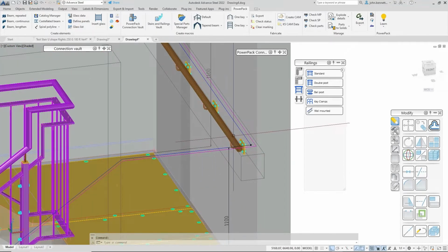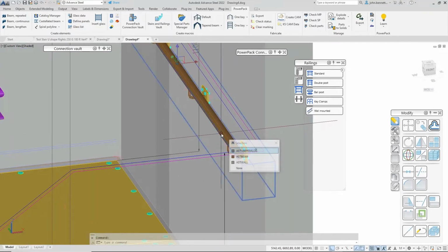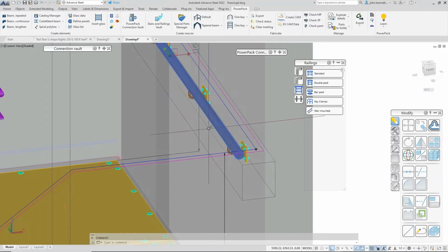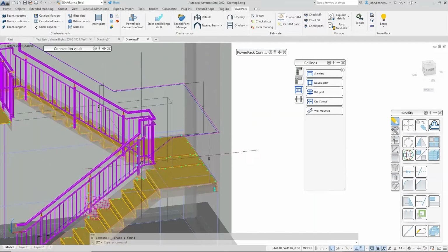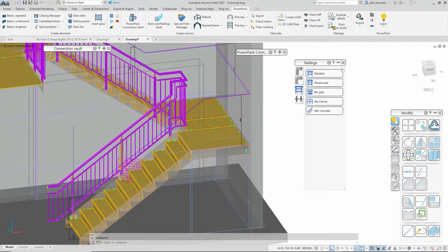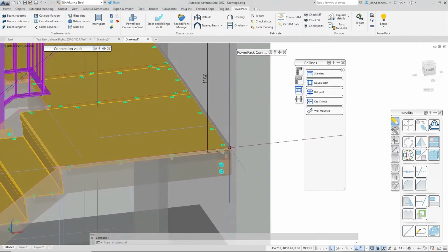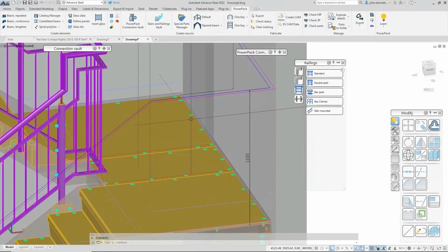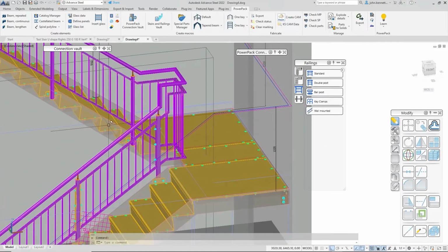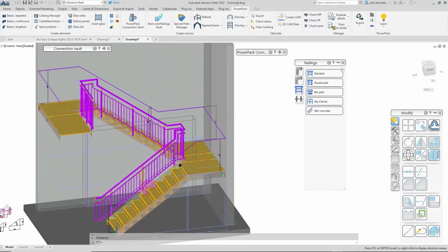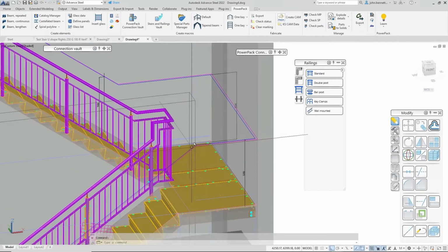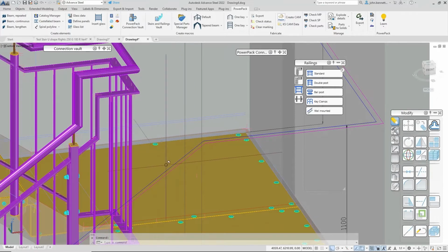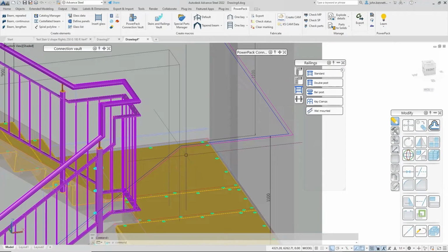So you saw me pick the line there, and the first question is probably how did you get to the line? All I did was draw a line up the side of the staircase and around the landing using the internal edge, because it gave me some nice corners to fix to, and mapped that all the way around, and then moved that up to the appropriate heights required. It may be different between the inclined sloped element and the level elements around the landing.